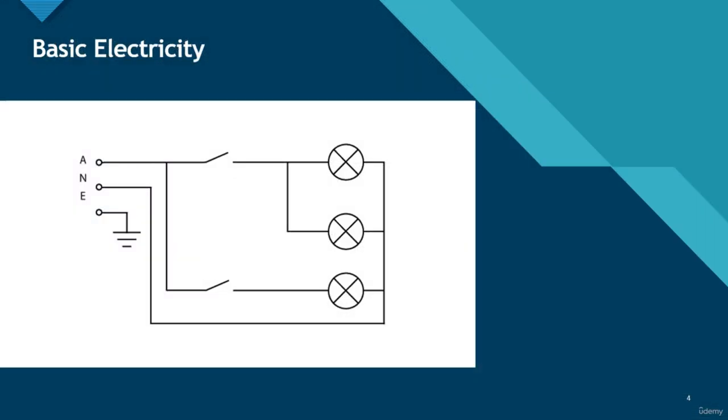And then here we have a basic electrical circuit. Let's, for example, use the 120 volts that you would use in the home. Here is the black wire, which is the power leg, coming and ending at a switch. This switch is called normally open, and there are switches that are normally closed, but this one is normally open.